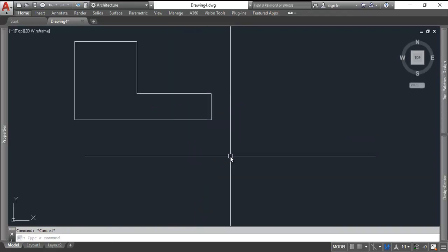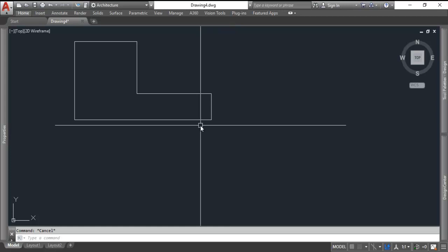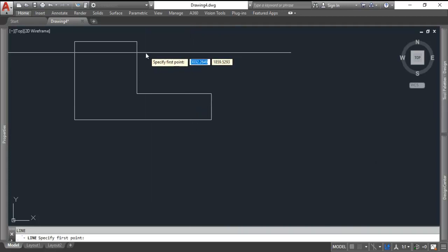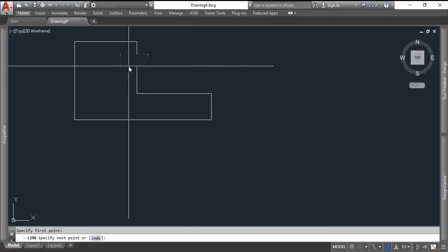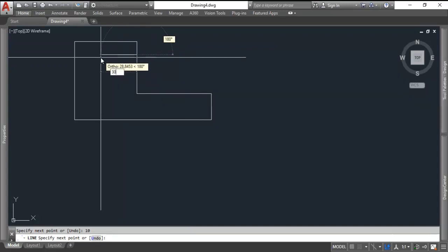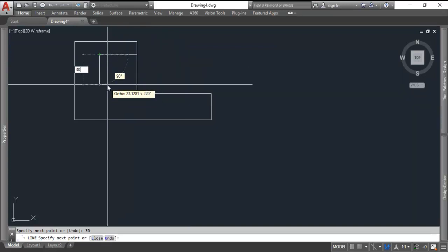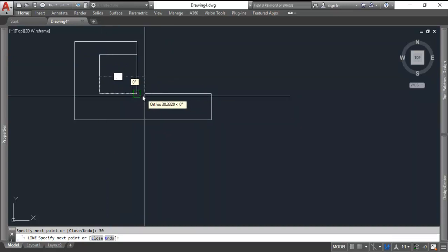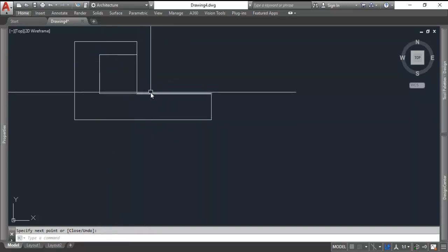So that's kind of our outline of the shape here, and you've got to be careful. It's a little bit confusing with hidden lines and center lines and whatnot. What we're viewing here appears to be a sectional view, but it's not, because our shape is not symmetrical. So we've got to be careful as we're interpreting this front view. So I'm going to simply come down 10, come over to the left 30, come down 30, and then come back. So that looks right, and I believe that's all of our solid lines.